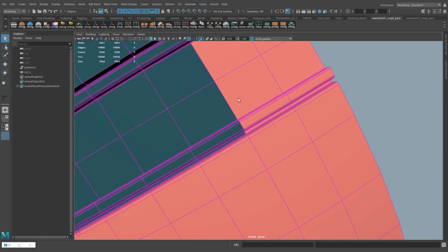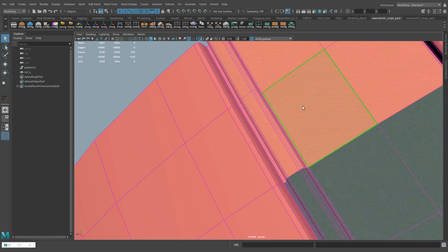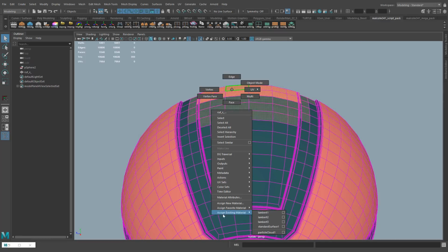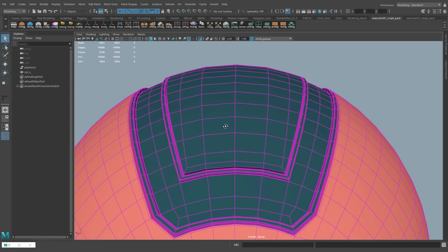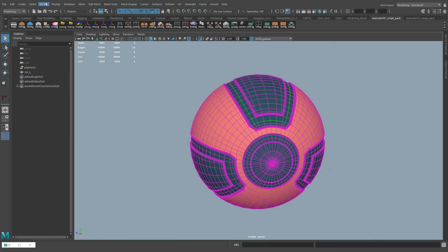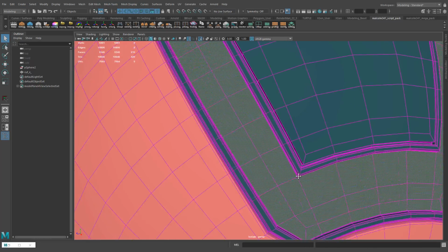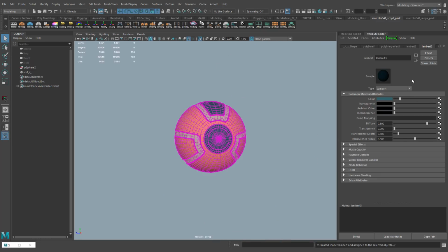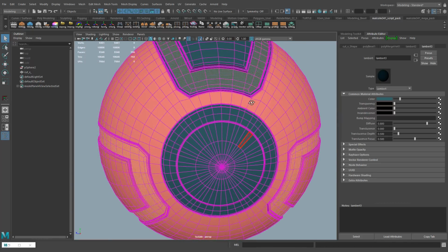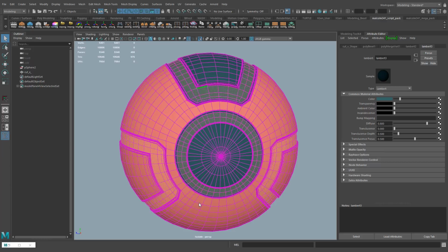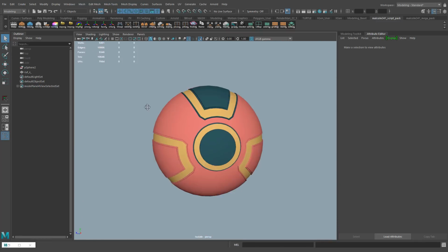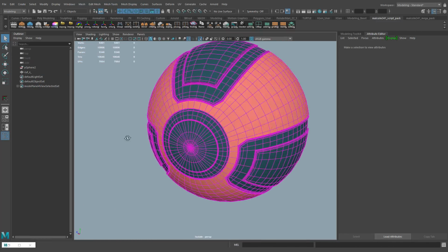So the great thing about this is whether you're using Maya, Modo, Max, or Blender, it's really easy to actually select faces at a relatively medium res mesh here, right? And apply different materials to then have Painter create this ID map for you. Instead of going in there and having to have a brush and paint and break this up. So it's exponentially easier to do this at this stage with a lower to medium res mesh, selecting polygons, assigning materials, right? Than to actually go in Substance Painter and have to do this with a brush, right? In my opinion, it's a lot easier and a lot cleaner.